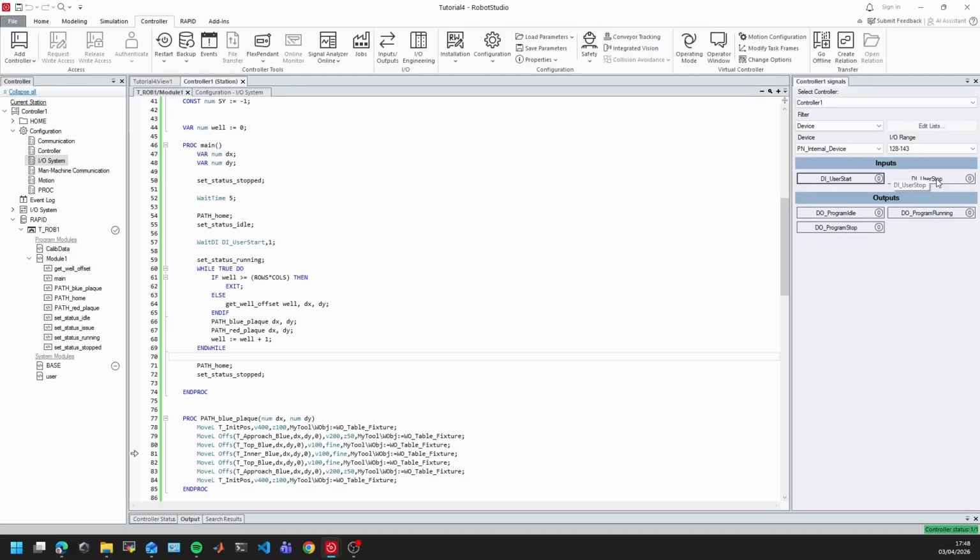But let's imagine that for the stop button, if I press it, in this case, I cannot simulate push buttons in here. But what I can do is try to simulate, like, okay, I do it very fast, the 1 and the 0. So just for the sake of this simulation, let's imagine that the stop button is a push button, a normally open push button. And what I'm going to do is I'm going to stop my simulation if my stop button is pressed.